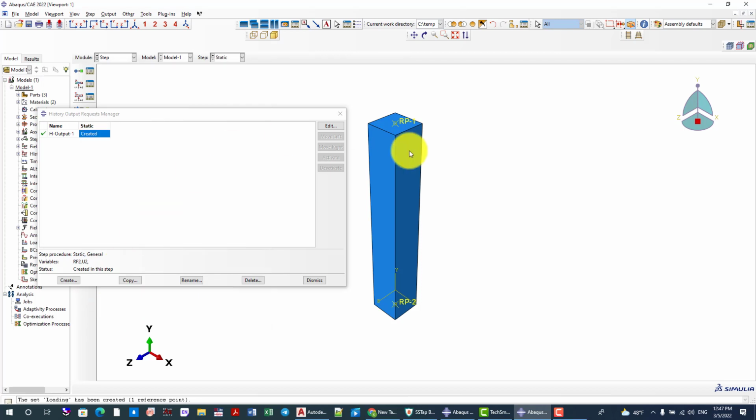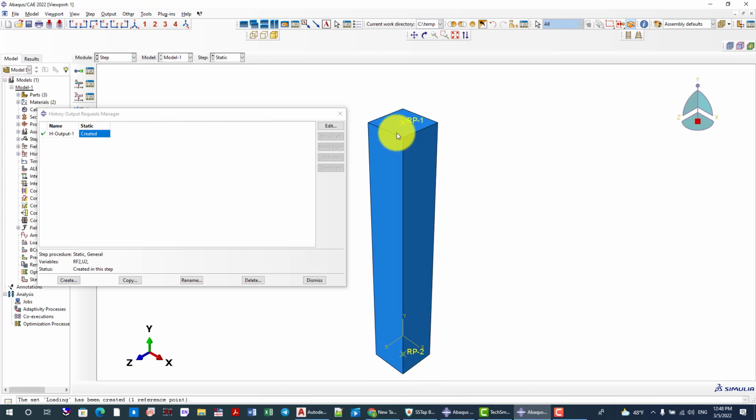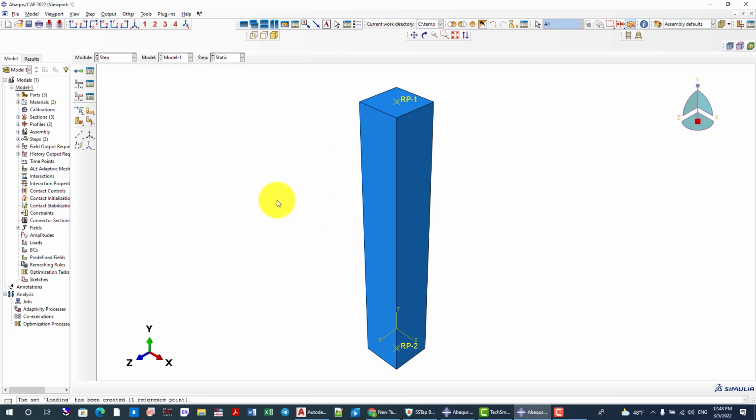So first we will apply the displacement. Actually we usually use a sort of device, then loader support, then pushing them down, and then there is some reaction force. So that reaction force in the finite element is equal from the bottom to here. And in the next step, instead of that pushing displacement, we will use the load which we got from this analysis, and then we will see the response of the structure.